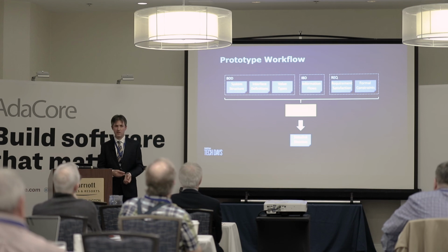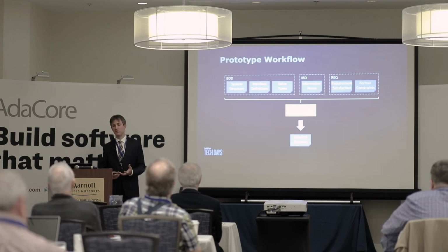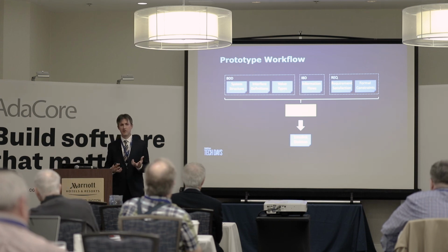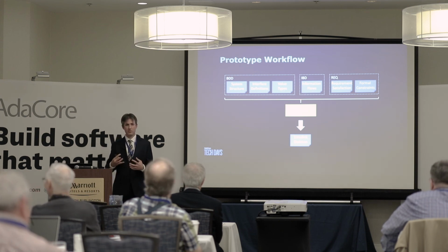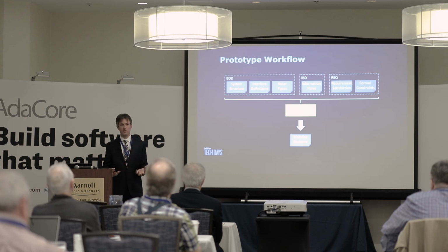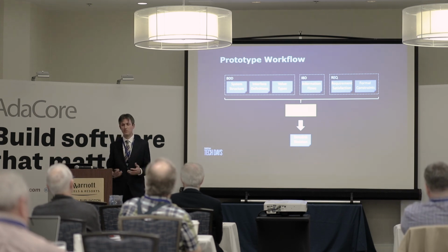So to get a little bit more detailed about this, we currently support the kind of information that you would typically specify in SysML using block definition diagrams, internal block diagrams, and requirements diagrams. We can take information about system structure, which shows the way in which components are composed. We can take information about interfaces, which tells you the kinds of information that flow into and out of a component. And we can take information about value types, which tell you the data types that are going to be exchanged by components, and use that to generate Simulink subsystems with ports that are correctly typed.